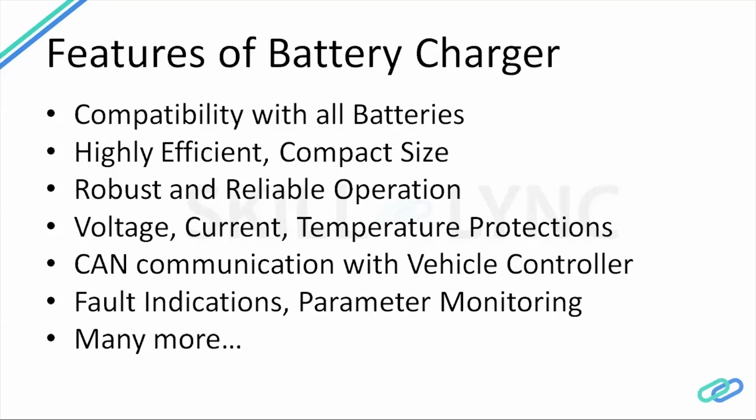Then we should have protection based on voltage, current, and temperatures to make sure of the safety of the charger and safety of the battery. Then we definitely should have CAN communication for communicating with the vehicle controller. Also, there should be indicators for various faults.